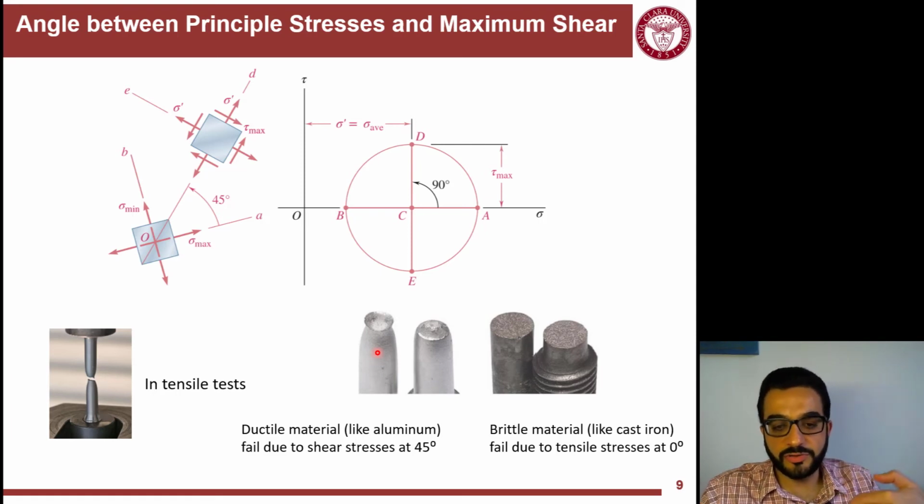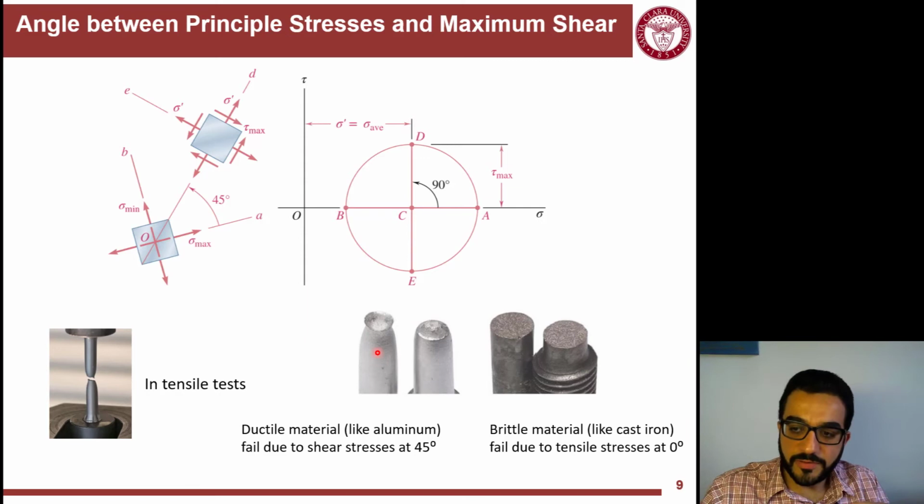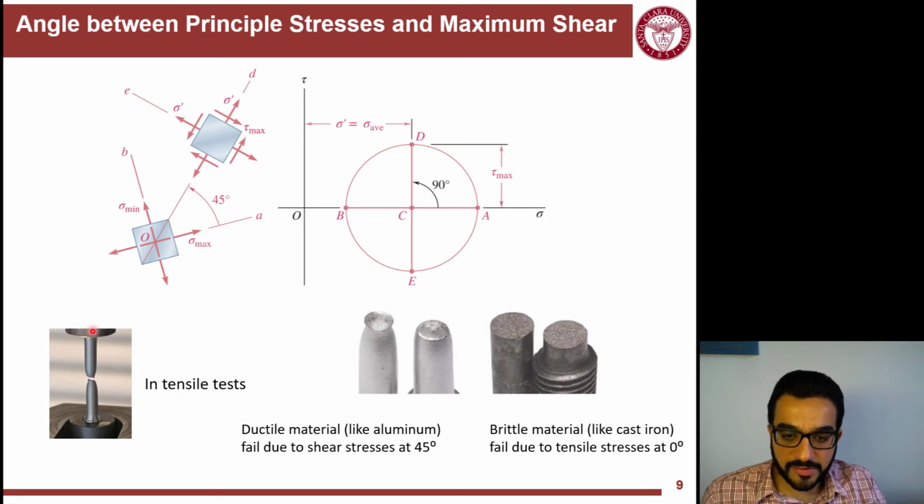So they exceed their shear capacity, and the shear failure here happens at the surface of the cone, which is actually 45 degrees. So in that loading case, I have only pure axial loads if I cut perpendicular to the axial load.